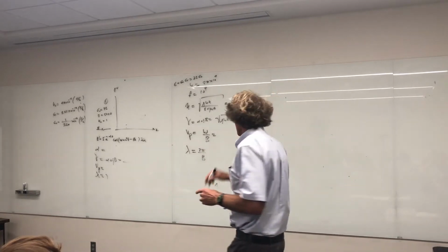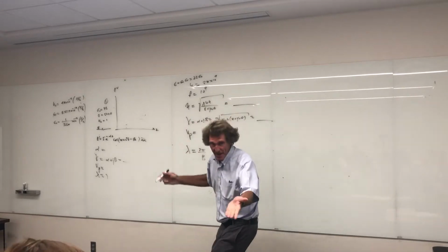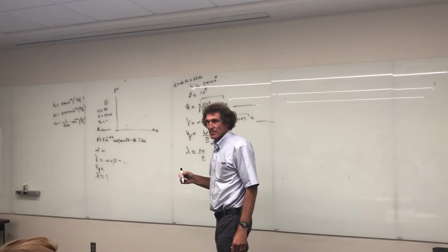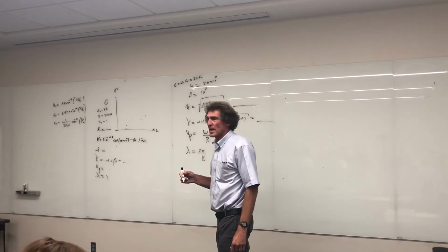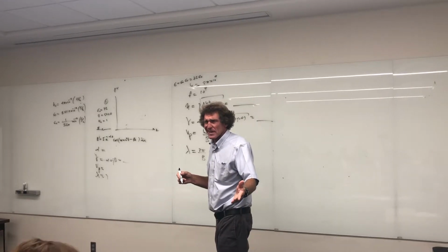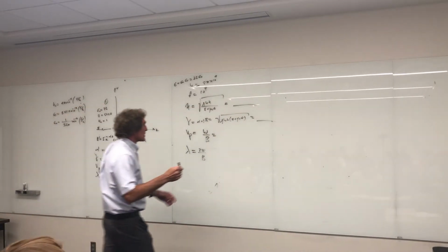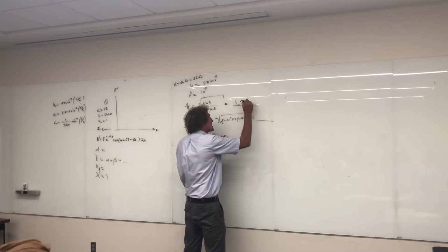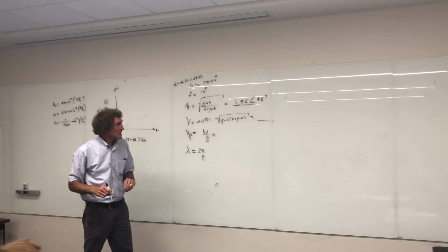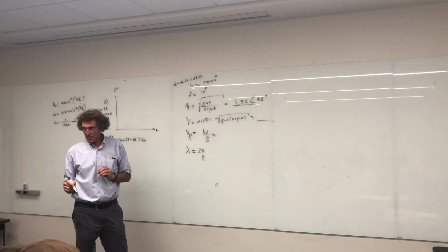I got a weird number. Give me eta first, if you don't mind. What do you have? That's a great number. What is it? 0.000132. Anybody else? It's a decimal. 0.0019. It's at 45 degrees. What did you get? I got 1.26 at 45 degrees. That sounds right. This is a good conductor, so it's going to be at 45 degrees. I can't guarantee. What about gamma? You're going to get alpha the same as beta, but what do you get for that?